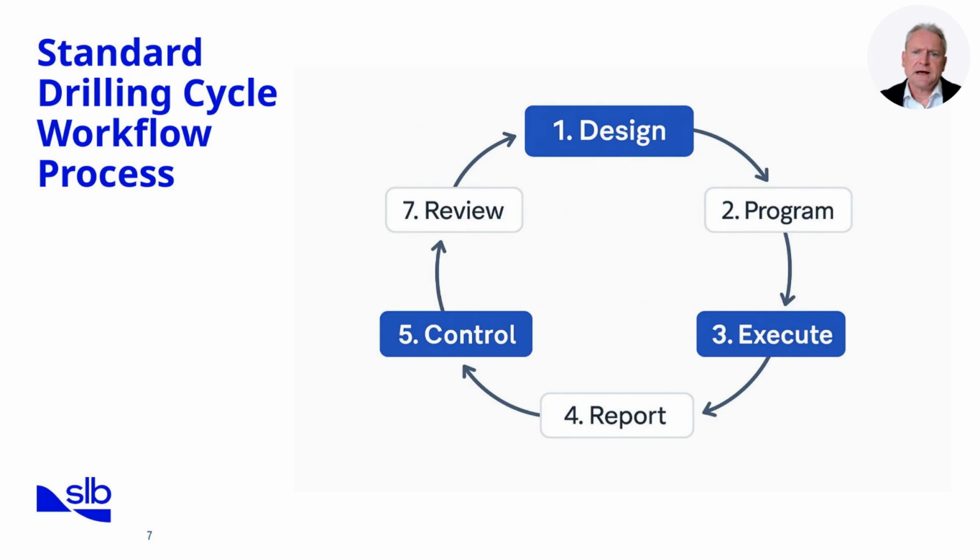When we talk about the standard drilling cycle, the process begins with design. Here, we define the well objectives, construct the well path, select casing and bit programs, and identify risks. The design integrates subsurface data, offset well performance, and mechanical earth models to build a safe, cost-effective plan.